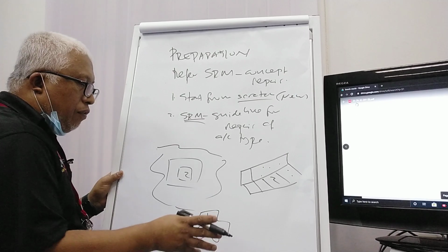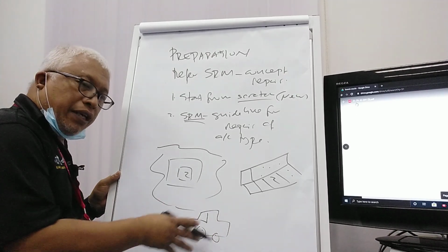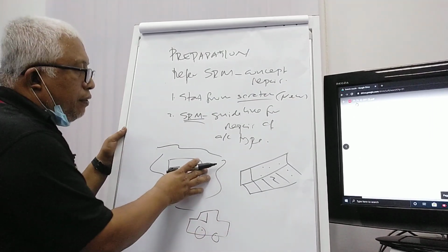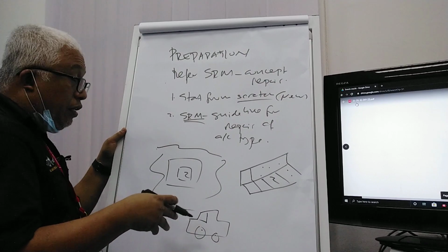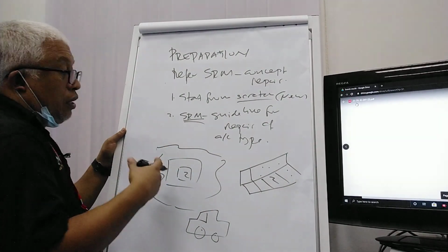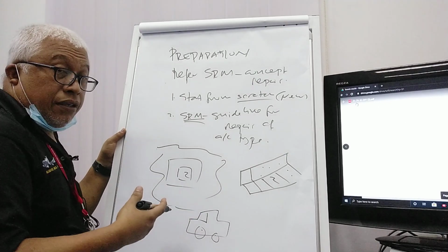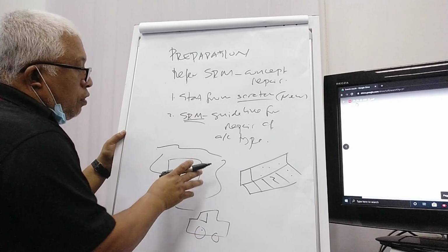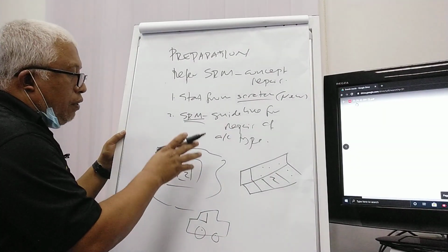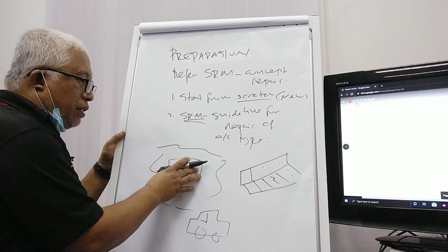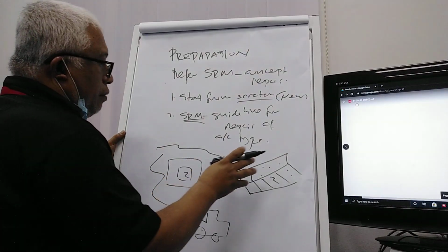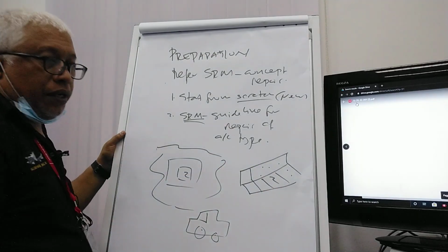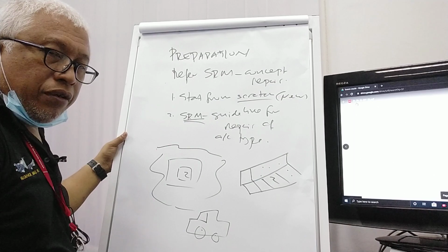If someone asks you to design a car, obviously you come up with the design. But for us as engineers, we can consider ourselves field engineers, not design engineers, because we are basically technical service engineers, trying to fix the problem as soon as possible. So if we have skin repair, we patch the skin, we make a patch doubler. If we have a stringer, stiffener, or angle, we do the same. We install a doubler and fasteners.